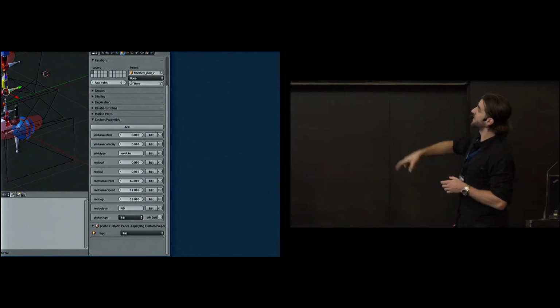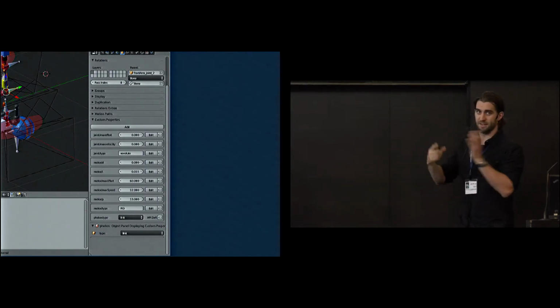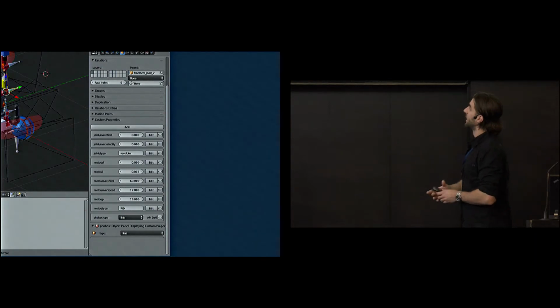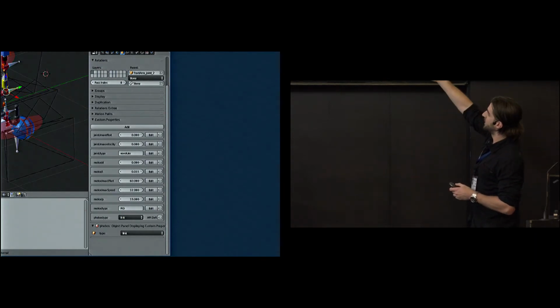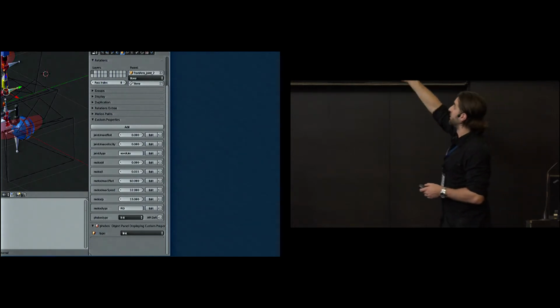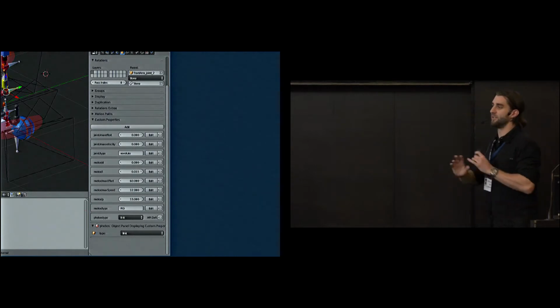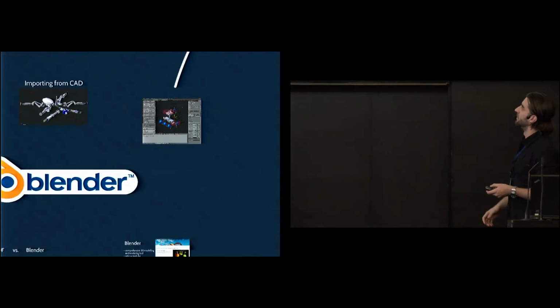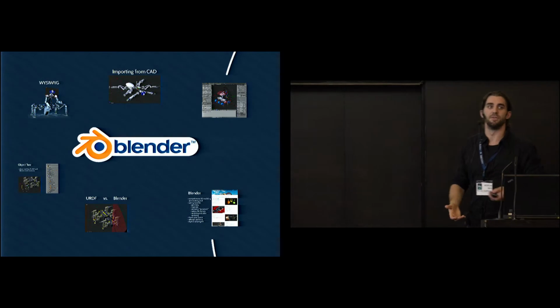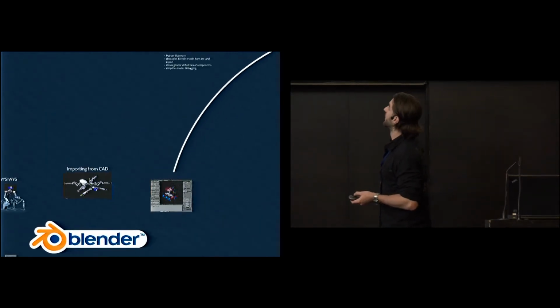So for example, in this case, we have this link up here, which at the same time, remember, is the joint, right? And we basically attach the motor by defining the maximum effort and speed of that motor, and by defining PID values for the controller. So everything really you need to know about your model can be represented in Blender, and it's a really cool tool for that kind of modeling.